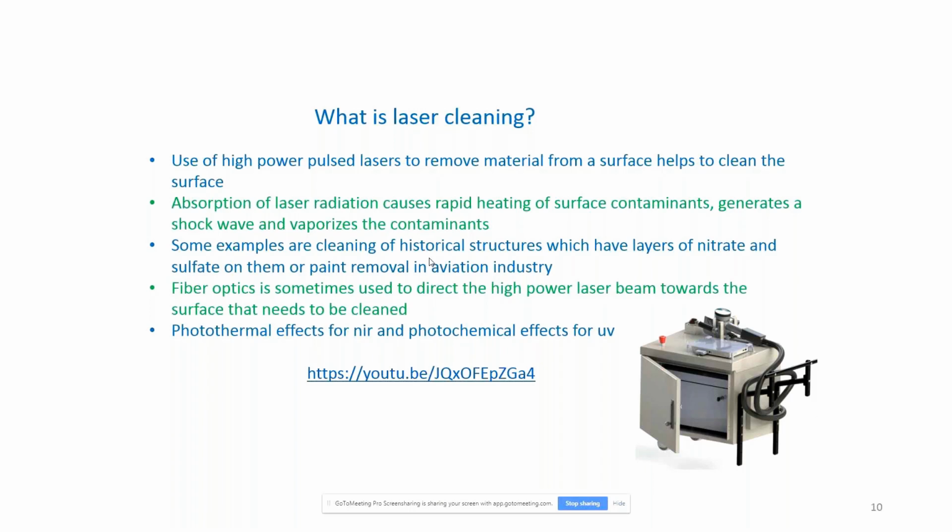Now, there are also different physical effects. Mostly for near IR it is photothermal. So it's all thermal effects, but for UV lasers, they're photochemical. So the laser actually dissociates the molecule. So in certain applications, it may really be required to dissociate the molecule. Just the thermal evaporation may not be enough.